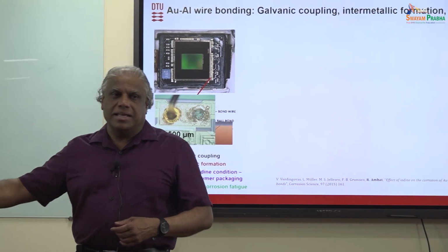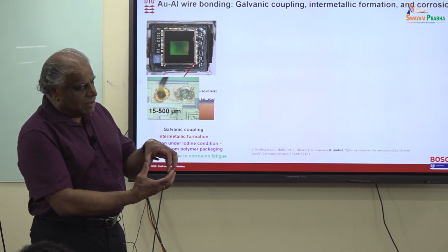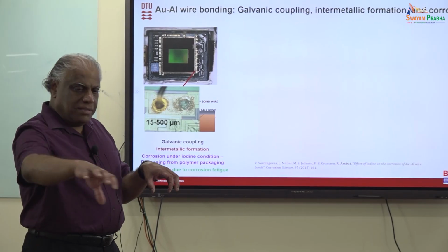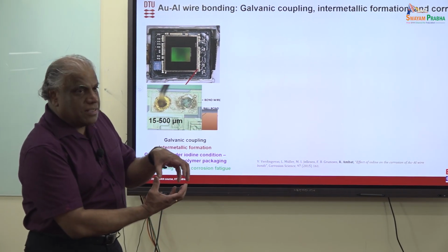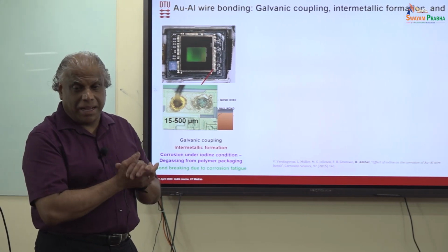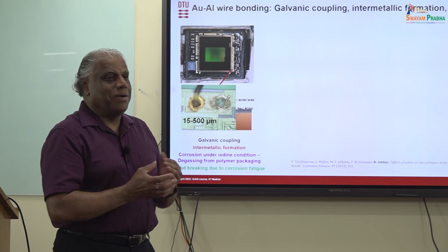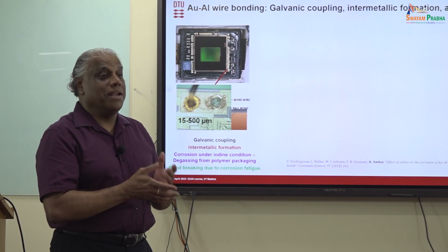Later they did a lot of analysis, and we were also involved. Then they realized the problem: this is an automotive IC, and the things to be analyzed have to come to this IC, so it is covered with a polymer tube. This polymer tube is made of polyamide. In the polyamide, potassium iodide and copper iodide are used as a stabilizer.